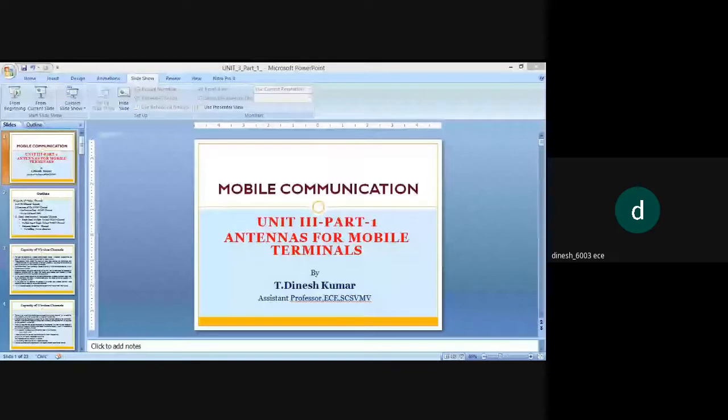So for different channel information assumptions, there are different definitions of channel capacity, depending on whether capacity characterizes the maximum rate averaged over fading states or the maximum constant rate that can be maintained in all fading states. Considering the flat fading channel capacity, the fading distribution is known at the transmitter and receiver. Meaning the receiver and the transmitter will know whether this channel is a flat fading channel or a frequency fading channel. So here we are considering it as flat fading. The capacity under this assumption is typically difficult to determine and is only known in a few special cases.